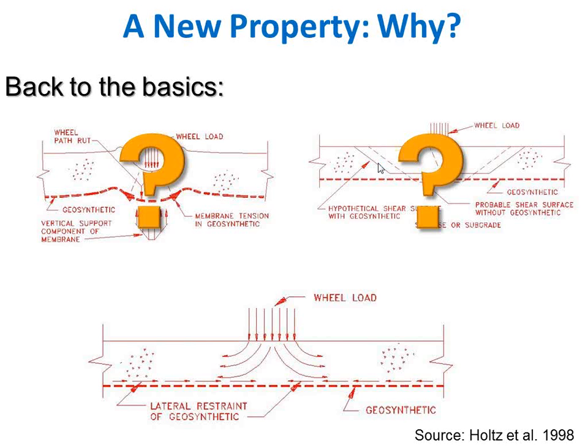The traffic loading is there. We're not going to ignore it. But the traffic loading is inducing permanent deformations. The permanent deformations on the base are the ones that are pushing the reinforcement laterally. But it's not that these lateral deformations are cyclic. The load that causes these permanent deformations is cyclic, but the permanent deformations are monotonic. The pavement doesn't swell and shrink, swell and shrink. It advances, small, millimeters.